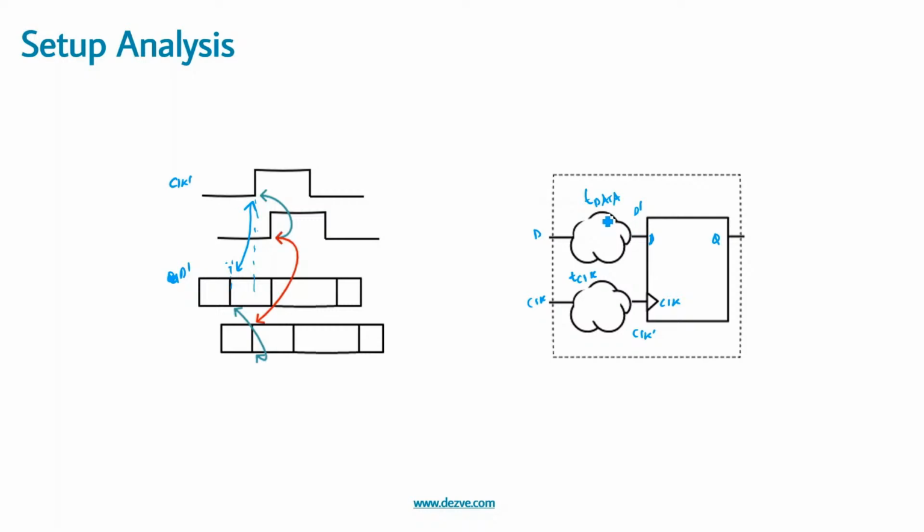But now assume that this delay is T clock. So the actual active clock edge gets skewed or delayed by this much amount. So the active clock prime edge would happen here, correct? Simultaneously, there is some data path delay which can cause the data to also be skewed. So data is getting delayed from here to here with the T data. So this was the original data, and we say that the skew between these is T data, correct? Now the setup and hold violation has to be considered with respect to these pins, correct?